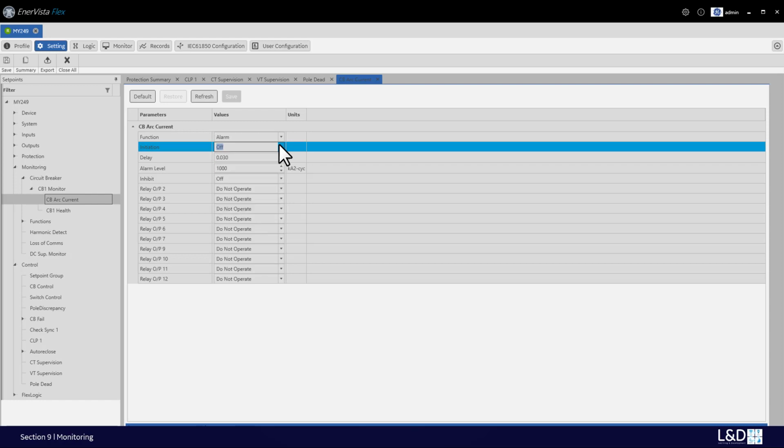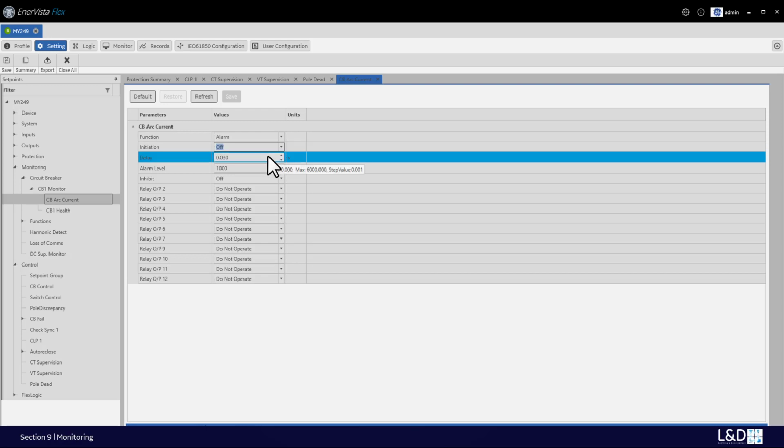The breaker opening has two stages: contact separation and arcing. In order to subtract the current through the pure breaker metal contact, a programmable delay is introduced between the initiation and the starting of integration to prevent false integration. This interval should include the operating time of the output relays, any other auxiliary relays, and the breaker opening. For maximum measurement accuracy, the breaker operating time should be measured with a breaker motion analyzer.